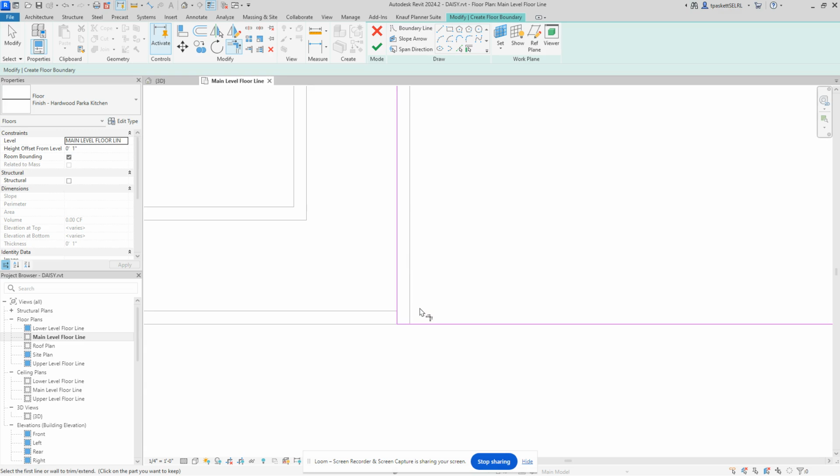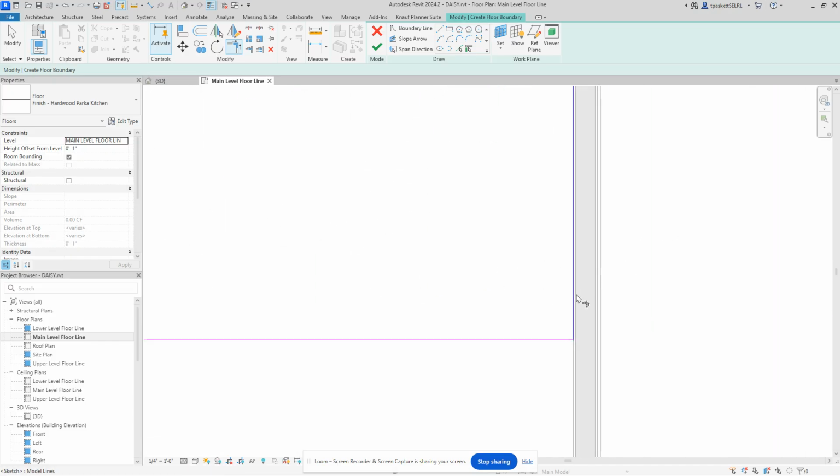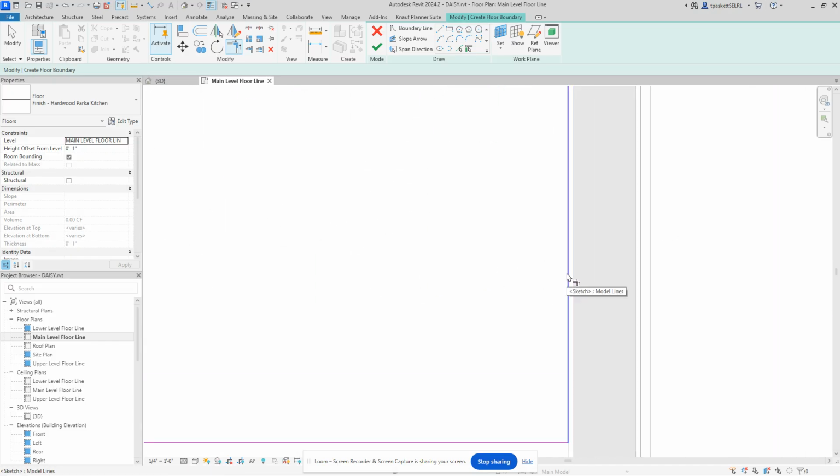Now there's one other error that Revit doesn't care about. It's on here, and that's off this wall where I picked a line, it picked the face of the wall. Overall, that's not a big deal. If that's what you do, you'll never see it unless they cut a section cut through it, and then you have this big white square where everything else is shaded and colored and looks pretty.